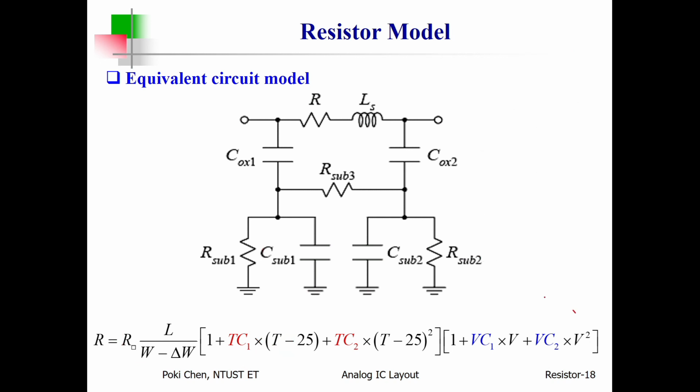The other bad impact is here. The resistor actually has not only temperature dependence, but also voltage dependence. It means that if the terminal voltage is changed, your resistance is also changed. Wow, that is really, really bad.